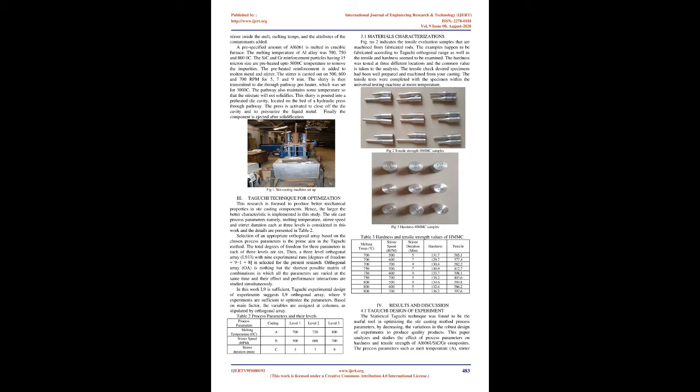An excellent wettability between solid ceramic particles and liquid matrix metal is necessary to obtain uniform distribution and satisfactory properties in HMMC. Alloying elements such as magnesium, lithium, calcium, or zirconium are included once and for all for wettability. Magnesium, along with enhancing the wettability, also increases the strength by solution strengthening the aluminum metal matrix composites HMMC. In a stir casting method as displayed in Fig. 1, the reinforcing phases, usually in powder form, are distributed into molten aluminum by mechanical stirring. The surfaces of both should be properly cleaned in order to minimize the reaction between the two, which may create impurities such as metal oxide and slag.